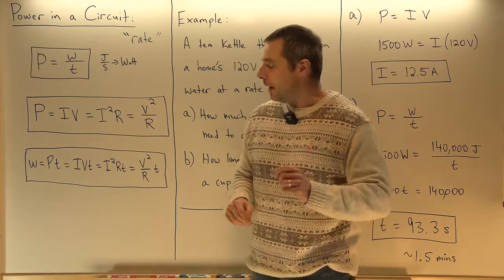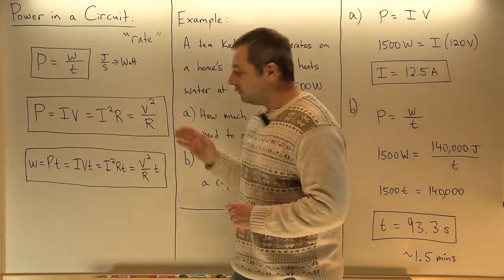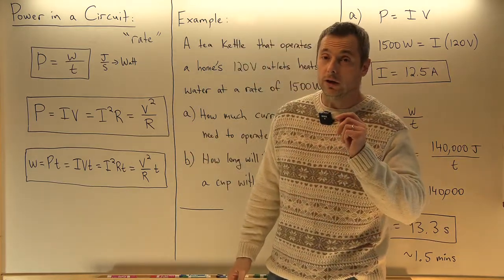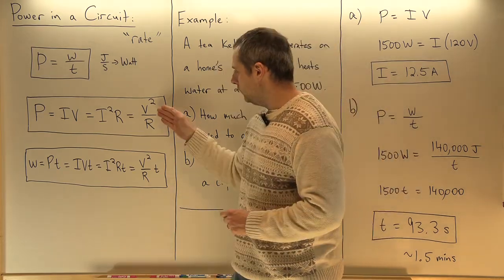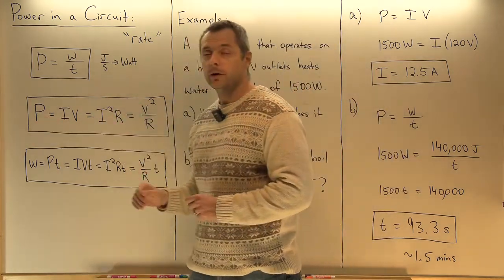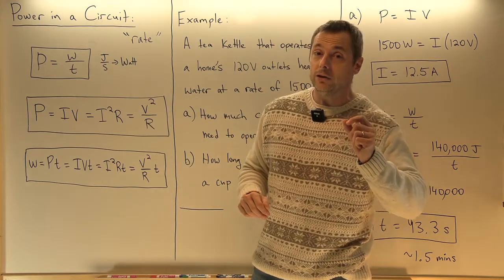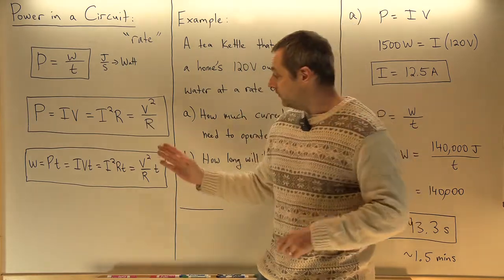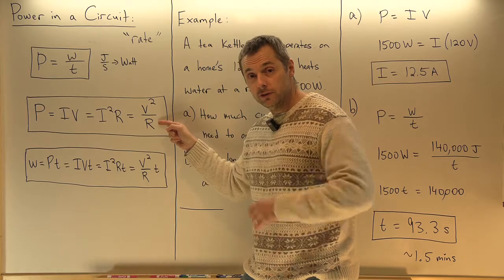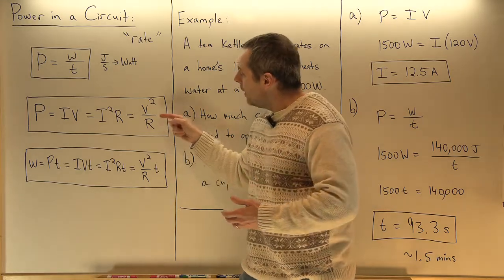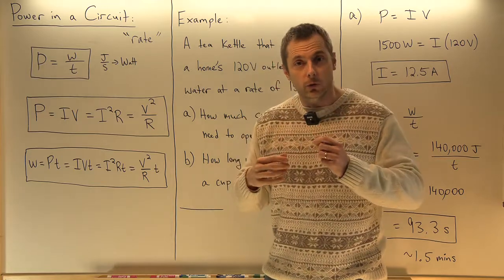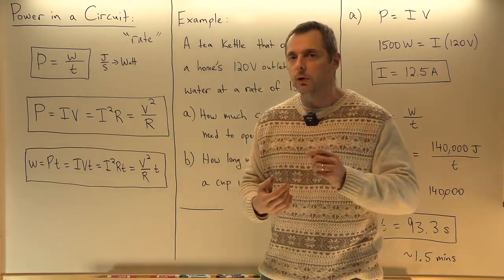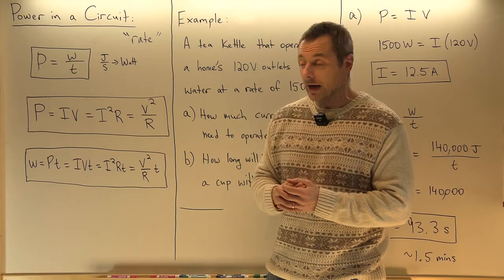But the other way to look at it is if the resistance is fixed. Let's suppose you take an appliance and you plug it into 120 volts, you get a certain amount of power coming out. But then you plug it into a higher voltage, same appliance, same resistance, same wires that it's made of. But with more voltage, the power goes up squared. So the power really builds up with voltage, the heat or whatever, the energy.